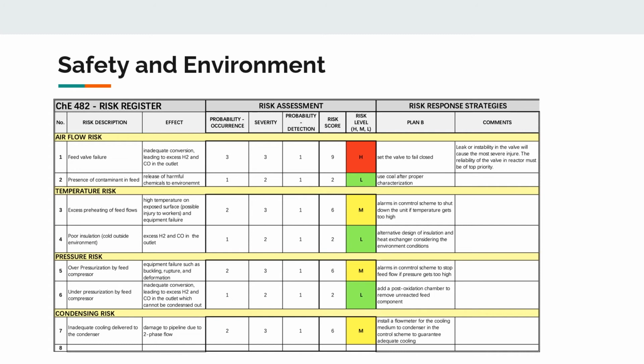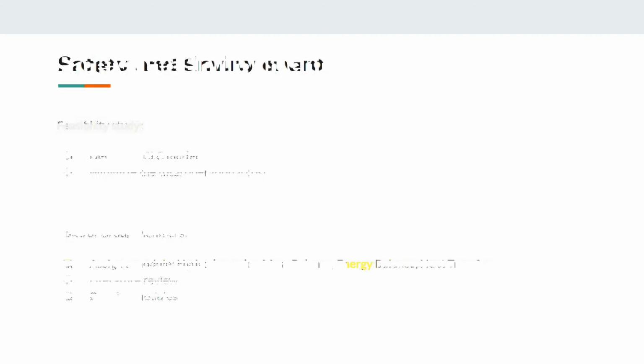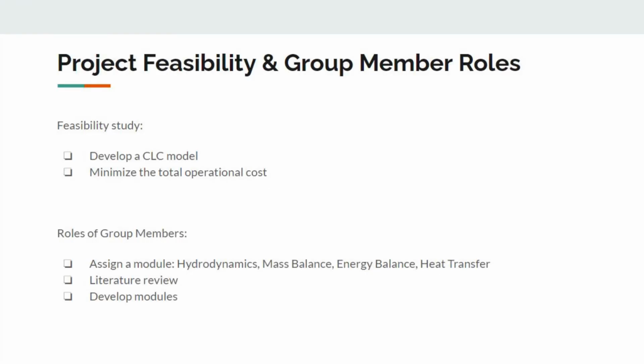From an environmental perspective, the CLC system takes ilmenite particles as the oxygen carrier, which has a lifetime of 1,700 hours before a replacement is needed. Although the CLC system can further facilitate the carbon capture process to promote a zero carbon footprint, the waste of oxygen carriers is an inevitable byproduct in order for the process to work. A possible approach to address the issue would be to harvest the waste carrier and extract the titanium dioxide for other commercial uses.